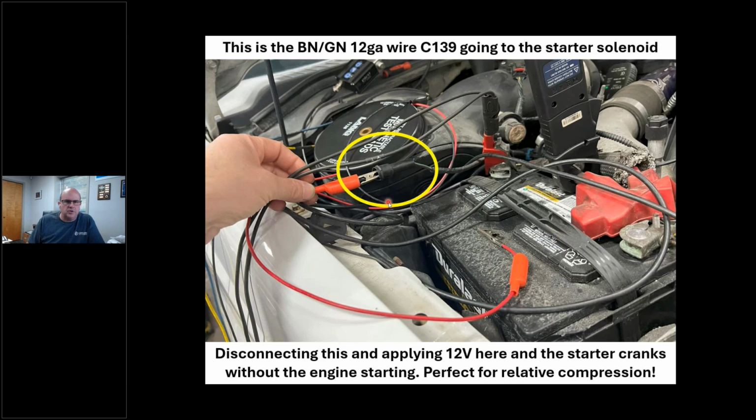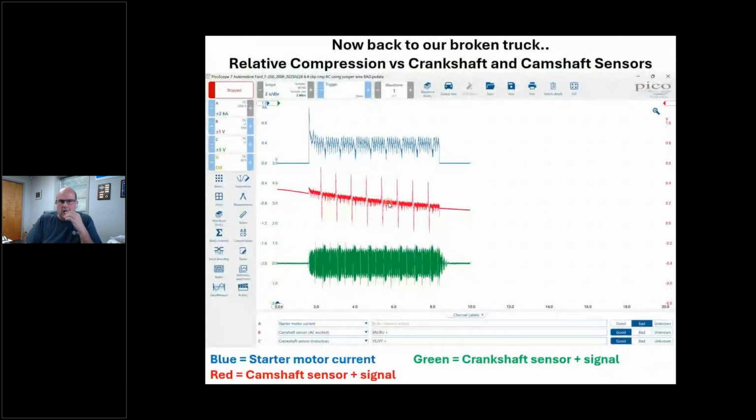I unplug it and I'm just going to use a jumper wire, okay? And I'm going to jump this thing because I don't want the engine to start necessarily, and I want to see what's going on. Okay. And I jump this truck. All right. And that's one good thing about AC sensors: I don't have to put power to them to make them work, so I don't have to worry about that. And I've got my amp clamp around my battery cable.